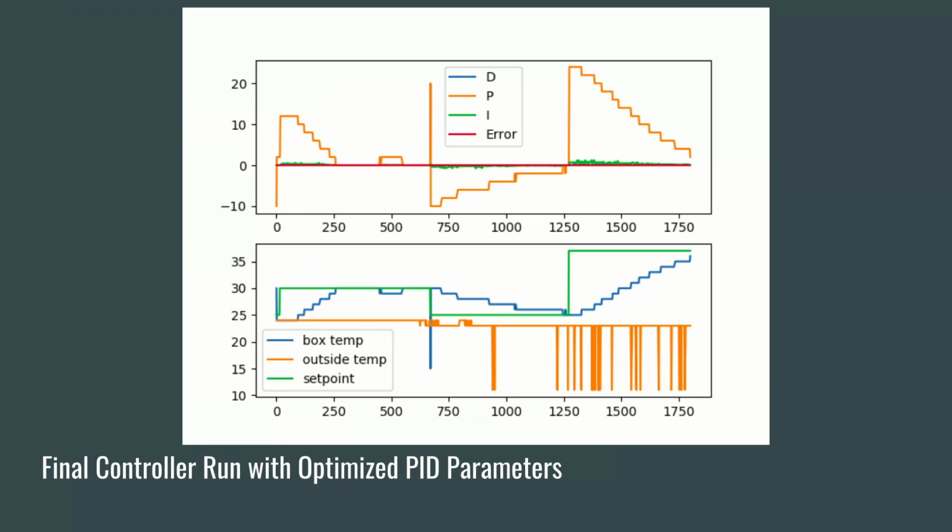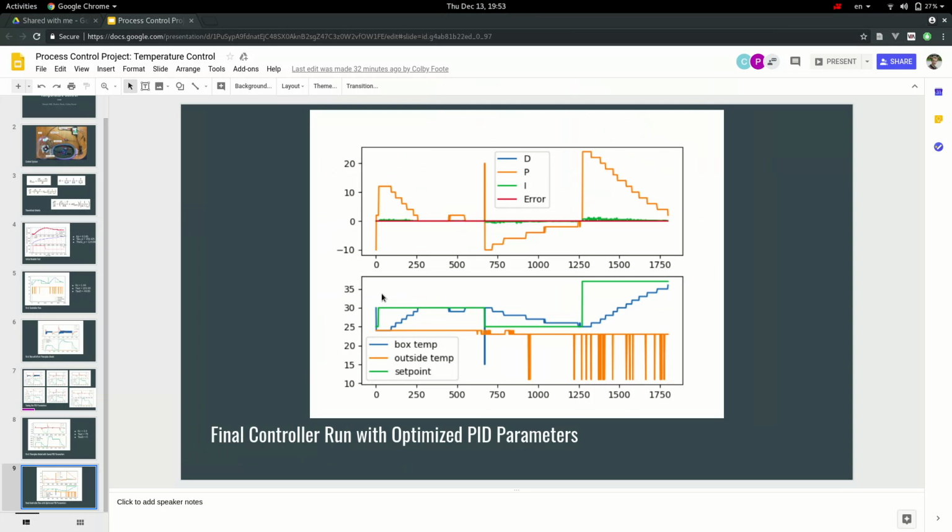And so here's the system being controlled with the actual final tuned parameters, and you can see that it's really controlling quite well, though of course the first principles model does not match the real system perfectly. And so basically we've created a fancy thermostat. A thermostat may even be a better solution in this case, yet for the group that we're developing this for, they likely will actually need these additional abilities.